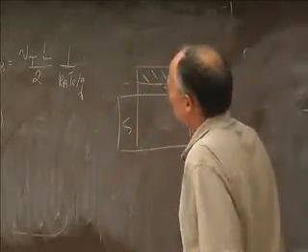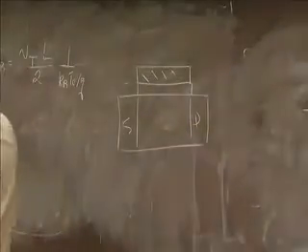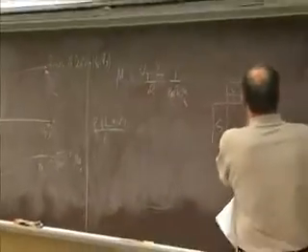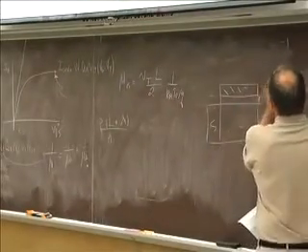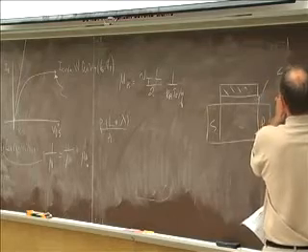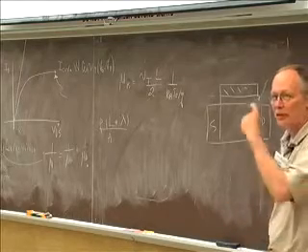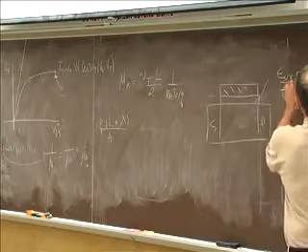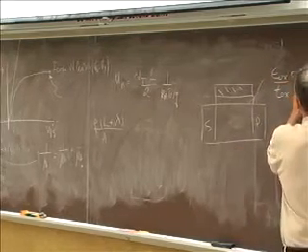When I've been talking about the gate capacitance, I've just written the oxide or insulator capacitance. That's epsilon of the oxide divided by the thickness of the oxide, which is a little over 1 nanometer these days. So this is the capacitance in farads per square centimeter.